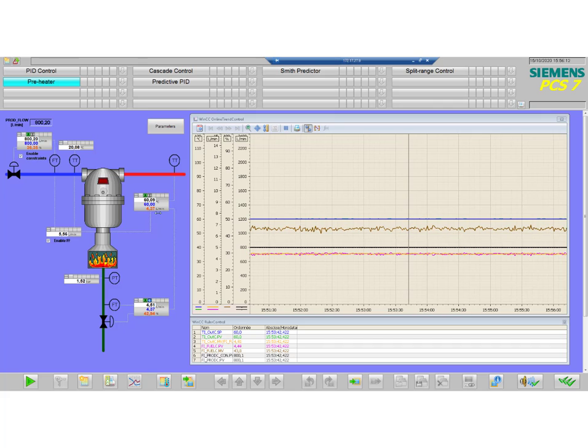Okay, so the controller subtracts more or less 1.1 liter per minute, and this is because in our feed forward we have used this K loss factor, not to have the ideal feed forward and have a realistic situation where you do not actually know perfectly the losses that you have in the system. And in this case, you can see that the controller will correct on the feed forward by adjusting everything in order to have the correct output temperature.